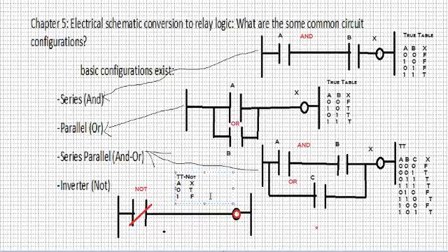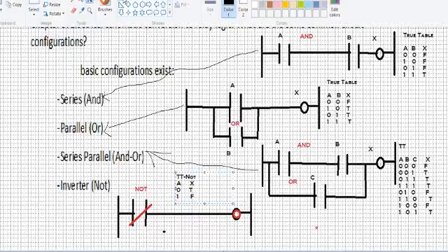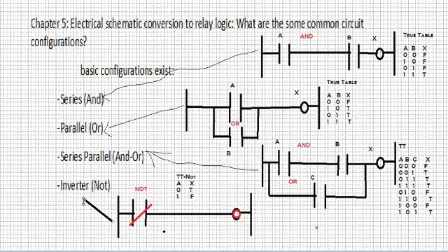And you just want to keep in mind the NOT instruction of the inverter inverts everything. So if it's closed, it will open when it's acted upon. If it's open, it will be closed when acted upon. And so anyhow, a lot of information, but we need to be able to understand this before we move forward to anything else. This is the basic configurations for relay logic schematic, and very powerful. If we understand this, it's going to come very handy when we come to the point.